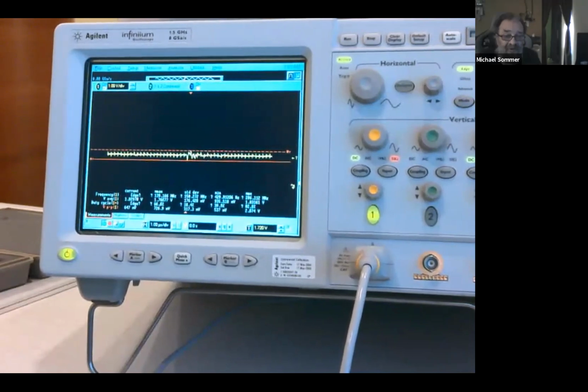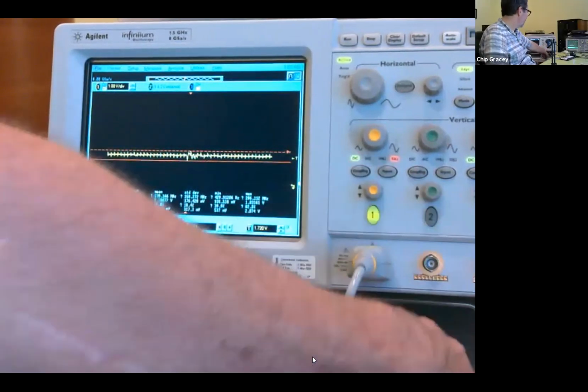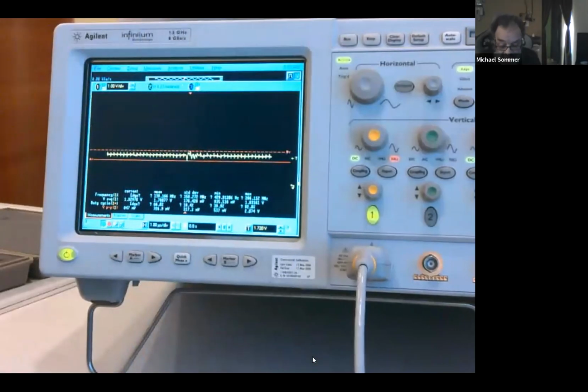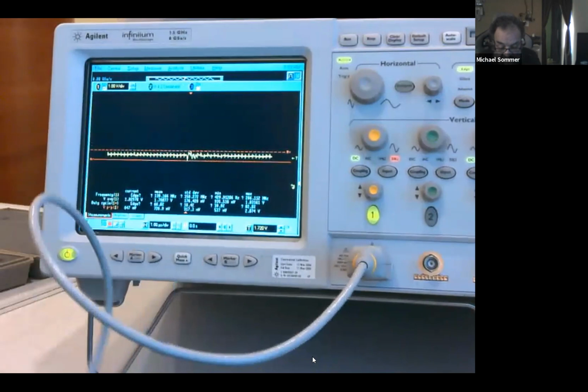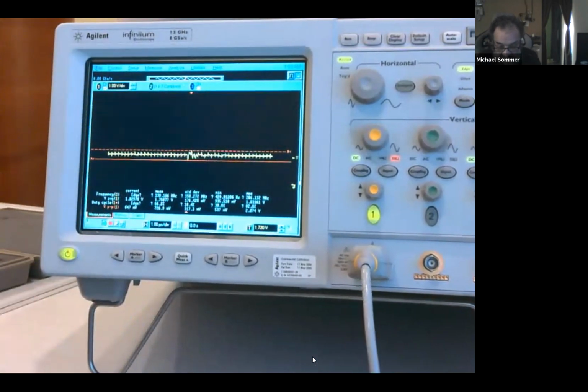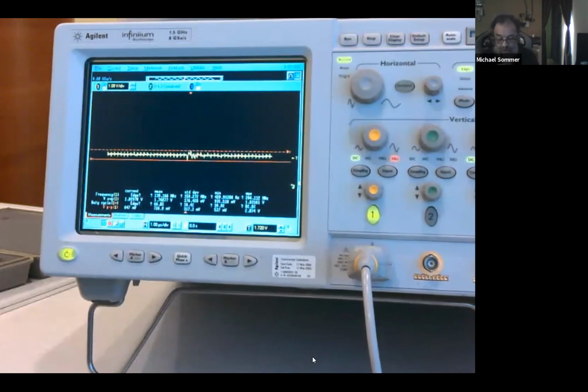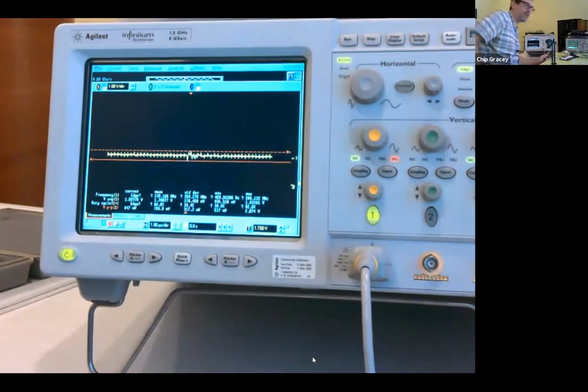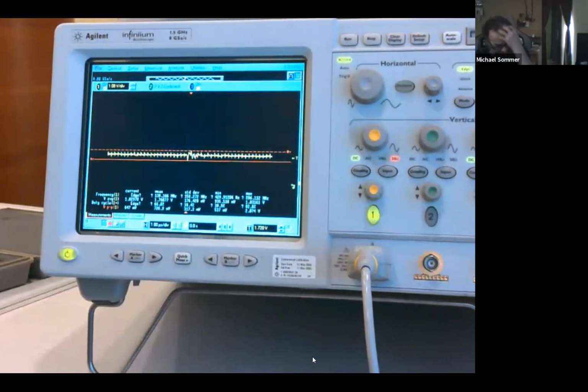Yeah, I have one. You said currently you have input voltage around 15 volts possible to the new edge? Yes. One very nice place would be automotive support, and in my opinion 15 volts might be a little bit low. Yeah. What we could do though is, you have sort of spikes in the automotive system which might get higher.